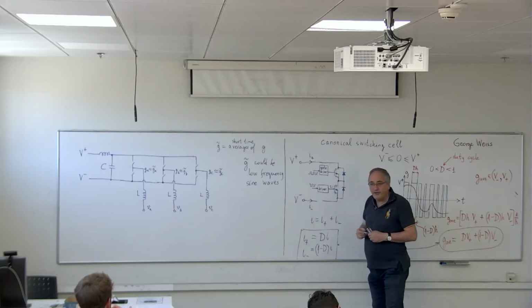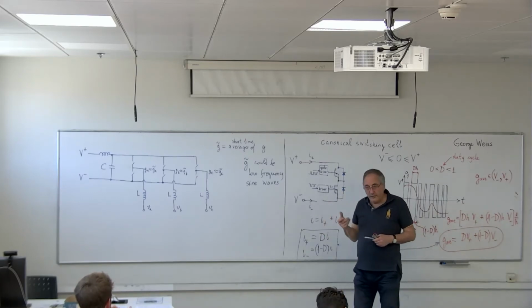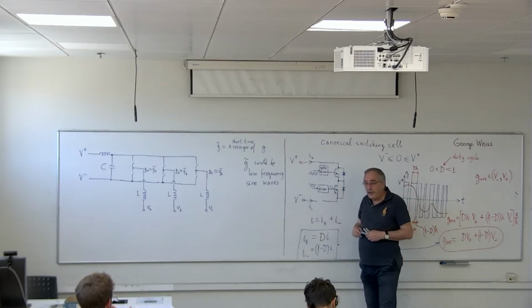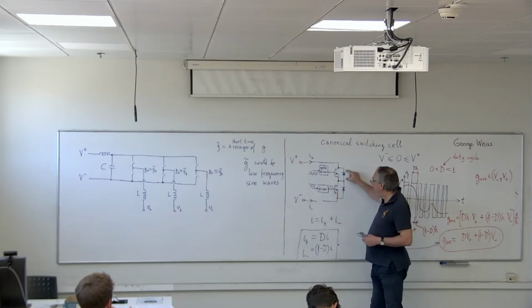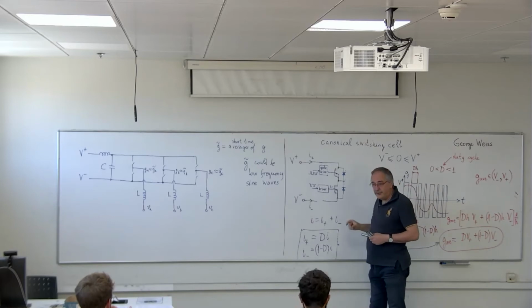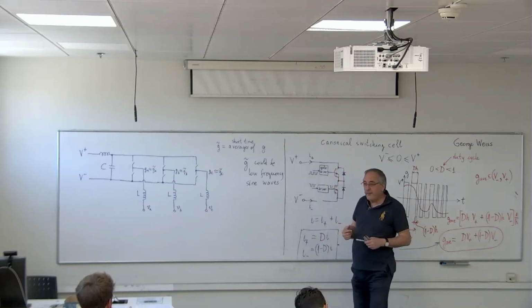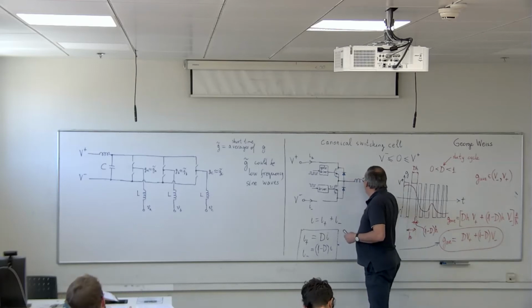And it is a bad quality diode, meaning that when it conducts, and then you want to stop it from conducting, so you want to switch it off, it will not switch off immediately. It will have some inertia. Even if you reverse the polarity of the voltage on this body diode, for a very short time, a few nanoseconds, it will conduct in the reverse direction. So it's a bad quality diode, which comes with the switch. And this is now the output, yeah?